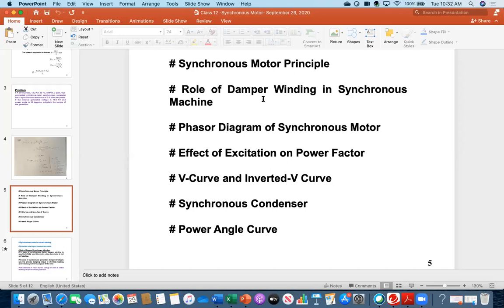On the other hand, the induction motor's speed is not always constant, especially if it is a wound rotor type of induction motor, then its speed is varying. Consequently, induction motors are used where you need variable speed operation. And the synchronous motor means its speed is constant. So those are applications like the paper industry and mill industry, where constant operation is needed, not variable operation.